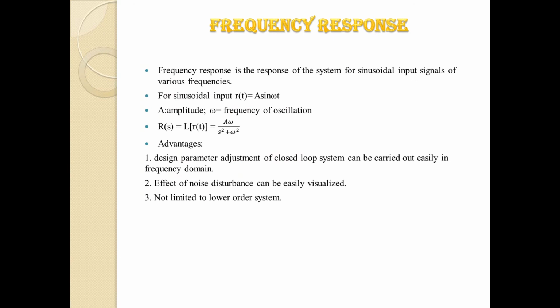First is the frequency response. Now, the frequency response of a system is the response of the system to sinusoidal input signals of various frequencies. Sinusoidal input is mathematically represented as A sin omega t, where A represents the amplitude and omega represents the frequency of oscillation.